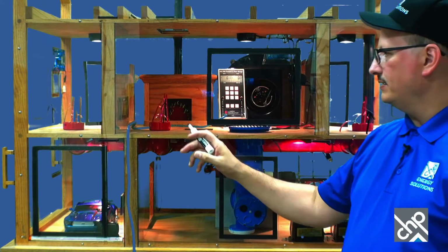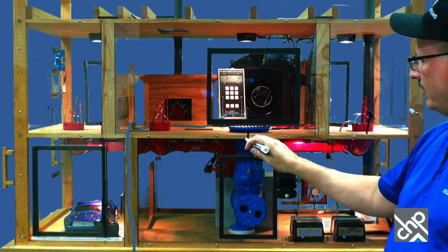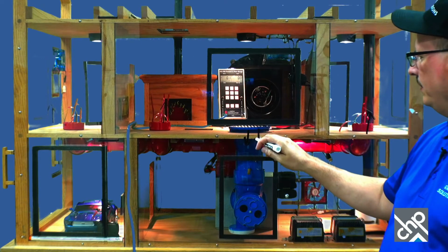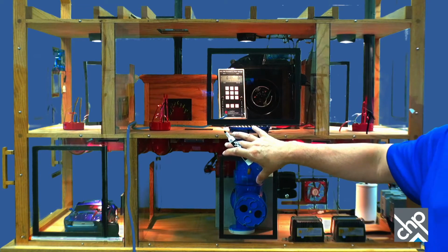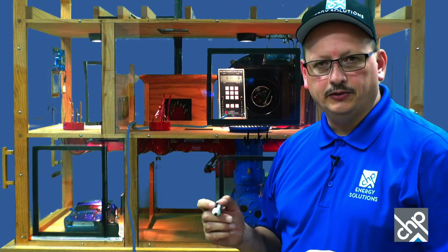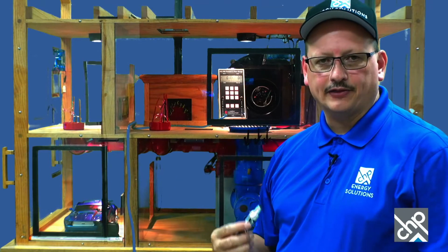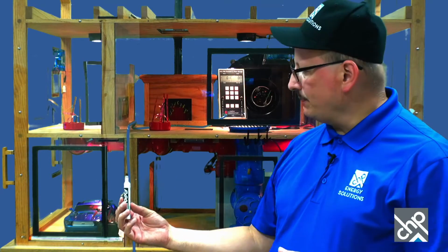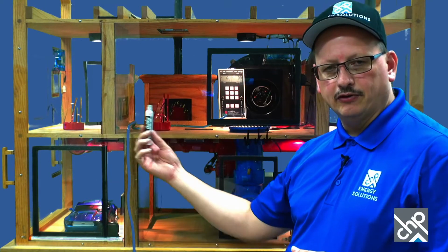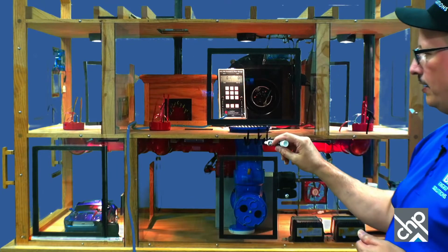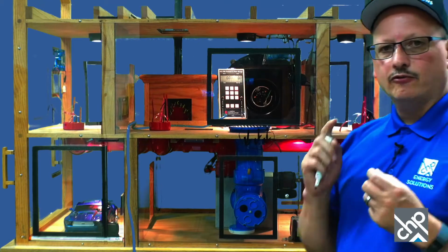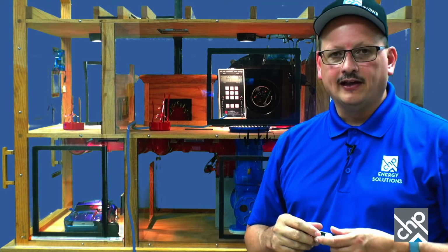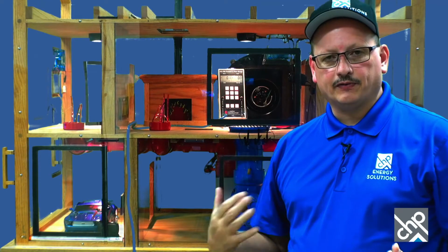So, that may show up. And then the return, which is right here. Hopefully these will show up. Basically, I've got 3 arrows on my return, and I've got one on each of the supplies. So I've got 3 supplies. That's to represent the air going into the room, those little arrows. And then on the return, I have 3 arrows, and that's to represent the return. I only have one return. It's what's called central return, and that's pulling back all the air for the whole system.